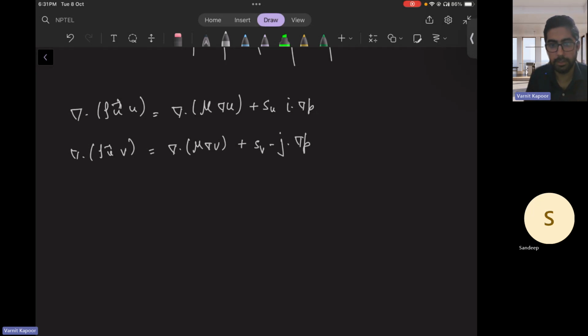SU is a body force. SV, suppose, is some miscellaneous velocity gradient. So these are our X as well as Y momentum equations. So we say that SU and SV do not just contain the body force terms, they also contain all the miscellaneous velocity gradient terms, which we don't write in the viscous terms. And depending on the value of the viscosity, we take all other terms and they will actually go to zero, as well as there's a possibility for that.